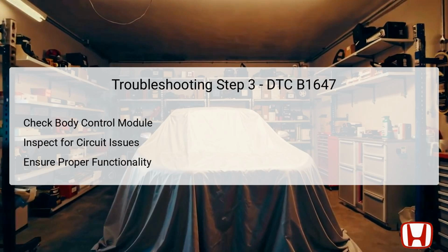In this step, you will focus on inspecting the body control module, which is critical to the operation of the LF antenna circuit. Begin by disconnecting the front passenger's door LF antenna connector and then conducting a module internal circuit inspection. Turn on the ignition to the appropriate mode and check for any voltage outputs. A normal inspection result will show expected voltage levels at the module's terminals.